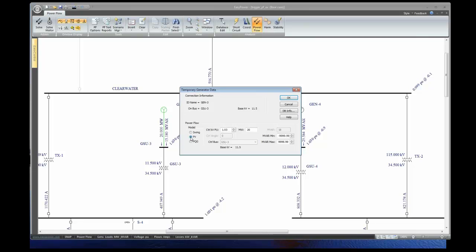So that's the PV, right? And this is analogous to a normal operating generator because this megawatts, what determines the megawatts, right? It's not the voltage, we already said that. This is determined by the prime mover. If I have a steam turbine, this is determined by the steam pressure, steam flow, which is determined by the control valves on the turbine, right? This is the amount of energy that you put in. So I can hold that constant while the voltage varies. And while other things are happening in the power system, that can stay relatively constant. So this is fairly realistic in terms of a real world operation.